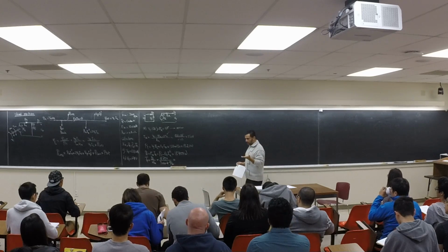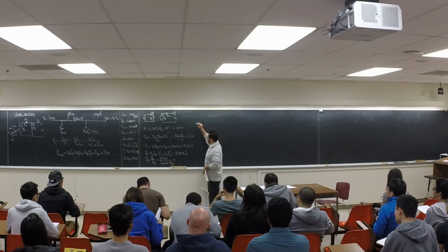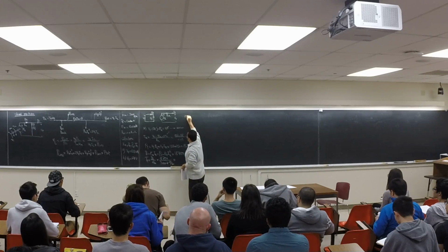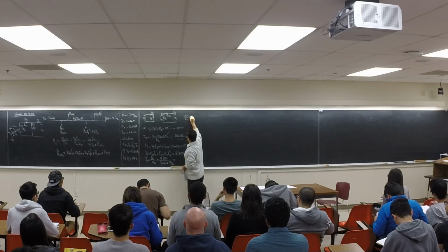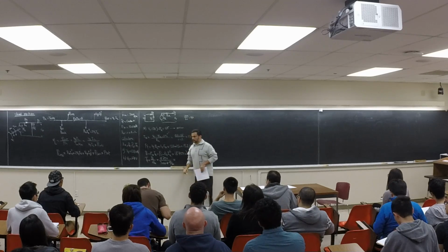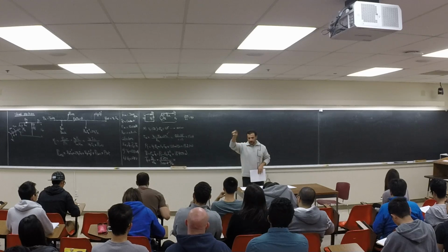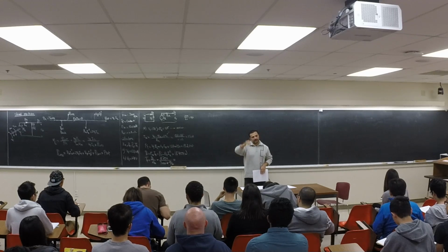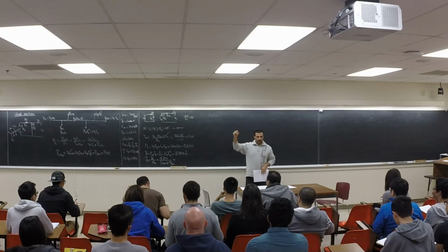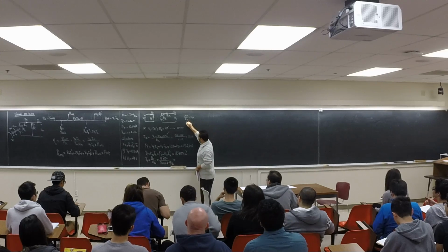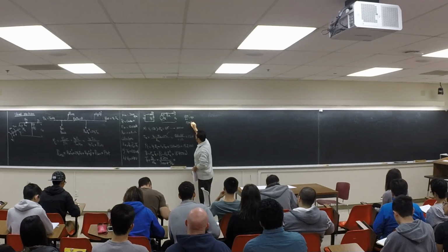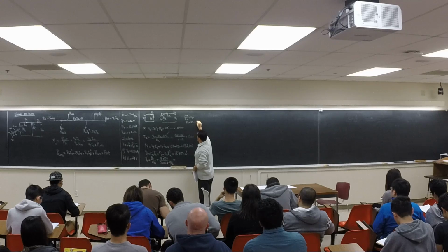So first you calculate the RPS: RPM divided by 60 is RPS, rotation per second. For every rotation, how many radians is it? 2 pi. So times 2 pi. RPS times 2 pi is radian per second.